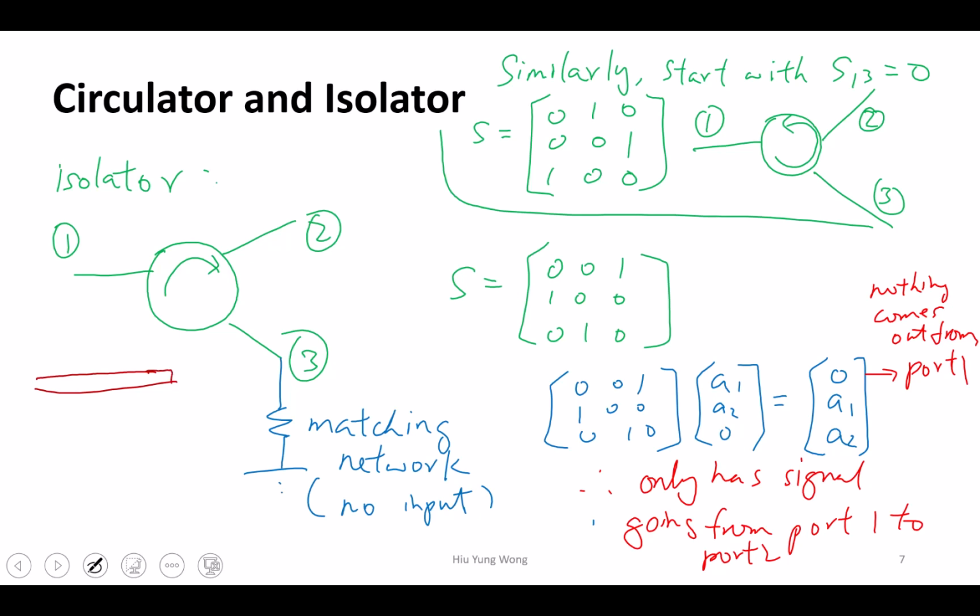But usually it is not infinite, and when you hit the boundary, it's going to get a reflection. It's just like the quantum mechanical wave, right? And if you terminate it with a proper impedance, which has the same characteristic impedance looking into it, then you don't get any reflection. So this is so-called matching. You match the impedance. Yeah, thank you.